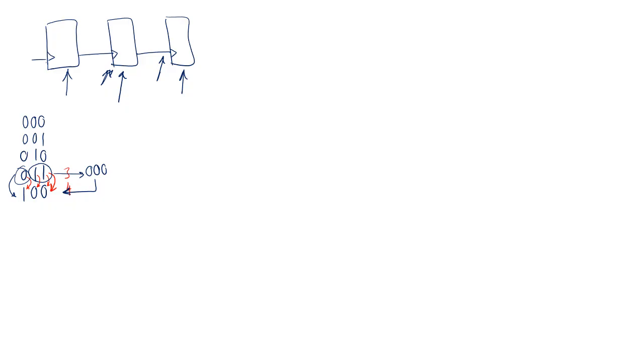Now, imagine going from 011 to 100, right? Imagine that the 0 to 1 transition of Q2 is happening sooner than the 1 to 0 transitions of Q1 and Q0. What will happen is that I'm going to get a 111, and then these two are going to go to 0, and I'm going to get a 100. And then imagine that the next block, connected to the output of your counter, is designed in a way that if you get a 111, that 111 triggers some other operation.